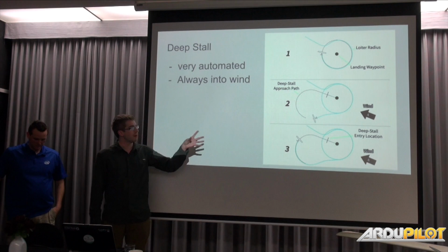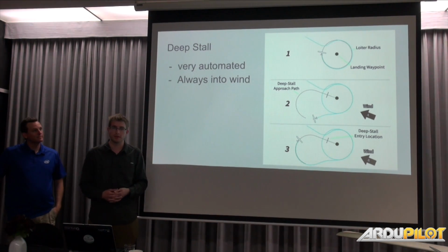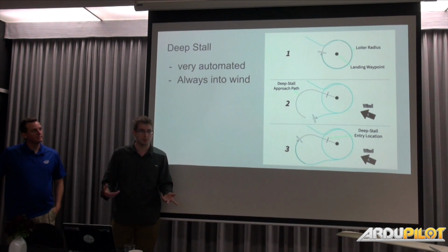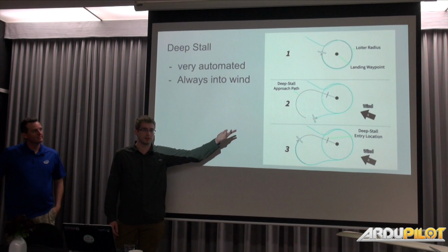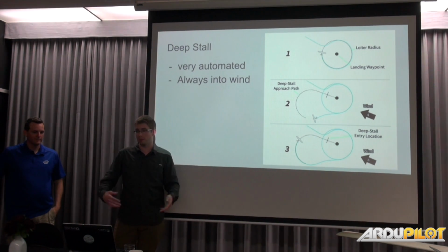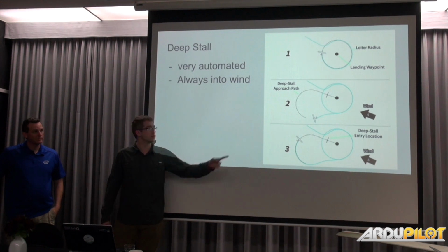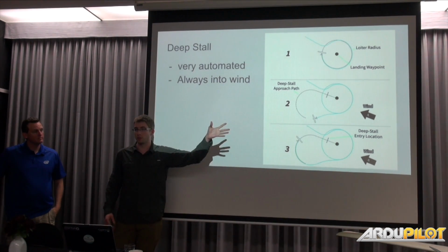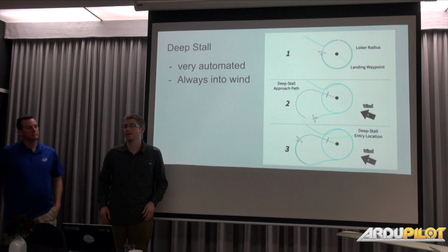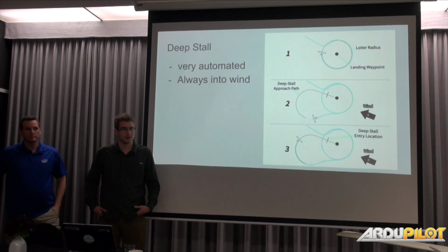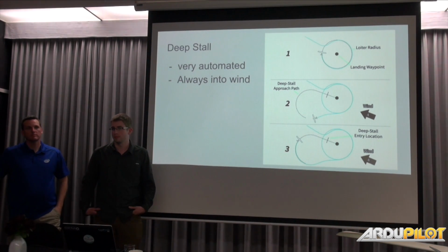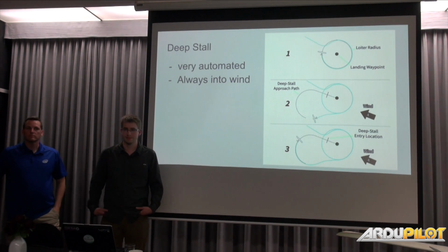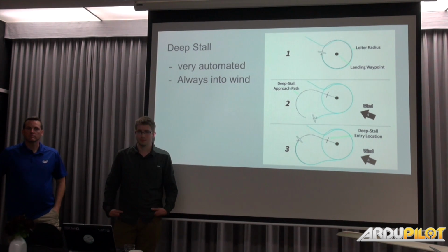If you think through what I'm outlining here, this is actually giving you predictive entry for parachutes as well. We don't support it at the moment, but this is predictive entry based on the relative wind for a point. Now this is using active steering, which the parachutes won't have. But you could use this logic to say, I pop the parachute here, and with this wind, I should hit there. Yeah, but also the tail sitters, the vector tail sitters particularly, are very appropriate. Might be cross when you transition. You just overwrite the predicted spot to your landing distance.